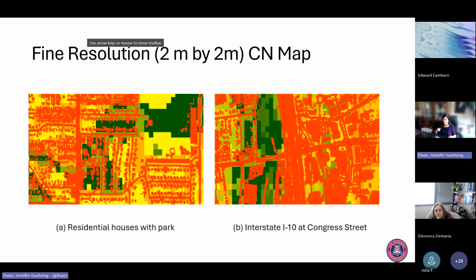All the rain coming to that cell, if your well is 2 meter by 2 meter, is going to go into the well until it is filled up. So there is no runoff out of that pond until it fills up.